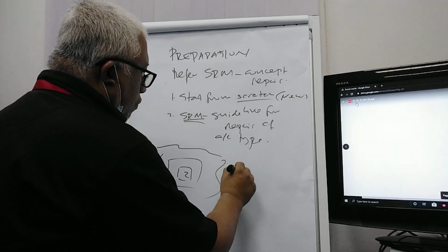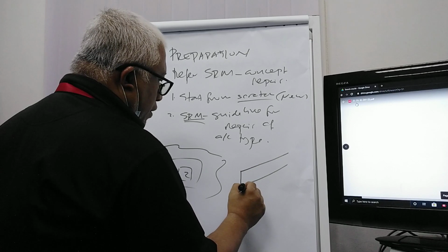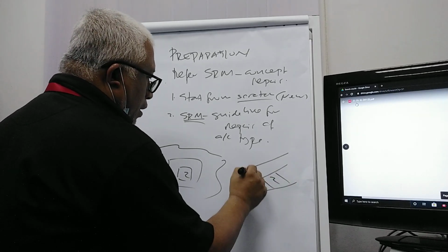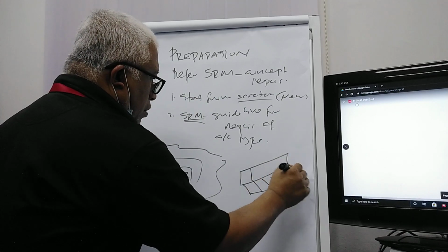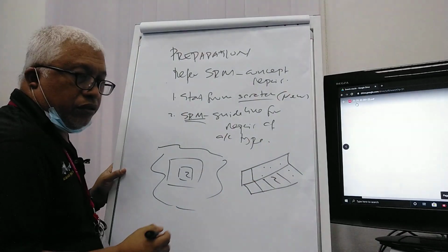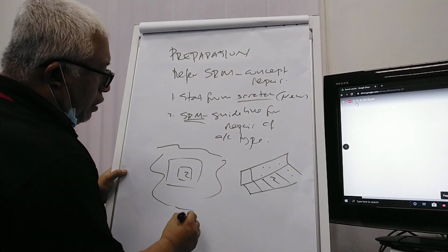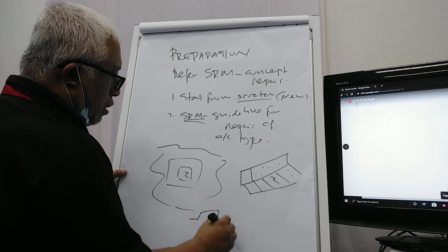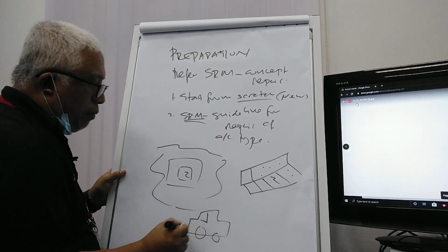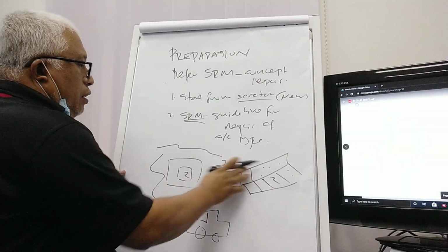We're not going to run away from the concept that if you have an angle, stiffener, or stringer with damage, you cut off and then you install a doubler. So this is a general concept. Just like if someone asks you to design a car, obviously we come up with a box where you put in the passengers and the driver. We have 4 wheels. So this is a general concept.